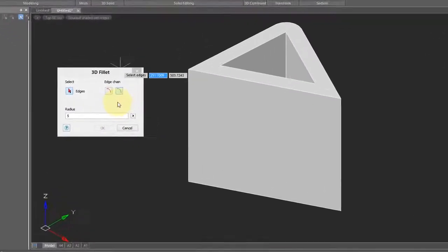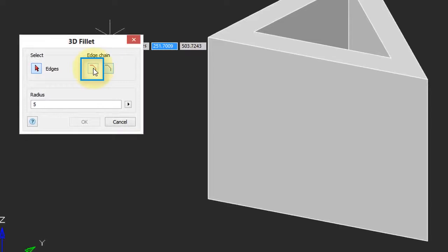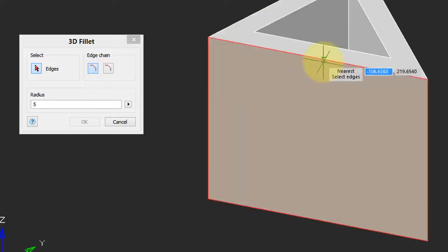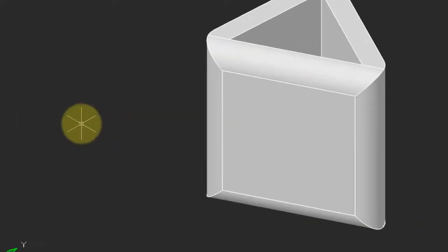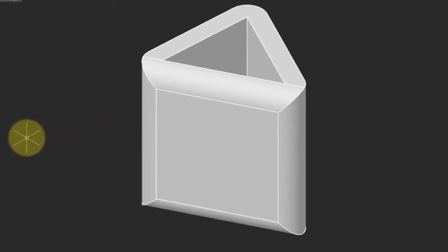The other way to place fillets on a solid model is to use the Face option. This places fillets on all the edges of the face you select. I move my cursor around and then click when a face is outlined in red. Again, nanoCAD previews the size of the radii, and I come over here and click, and all 4 sides of the face are filleted.